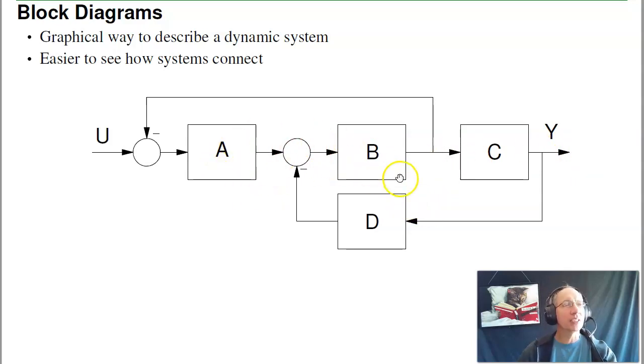I can sit there and build the system and try it and see, do I actually have a settling time of 4 seconds? Do I have 20% overshoot? It'll do other things as well. I can sit there and add nonlinearities, add noise, add a discrete time system combined with an analog system. Vissim and Simulink will do all that. So likewise, these are used extensively in the industry for testing your designs.